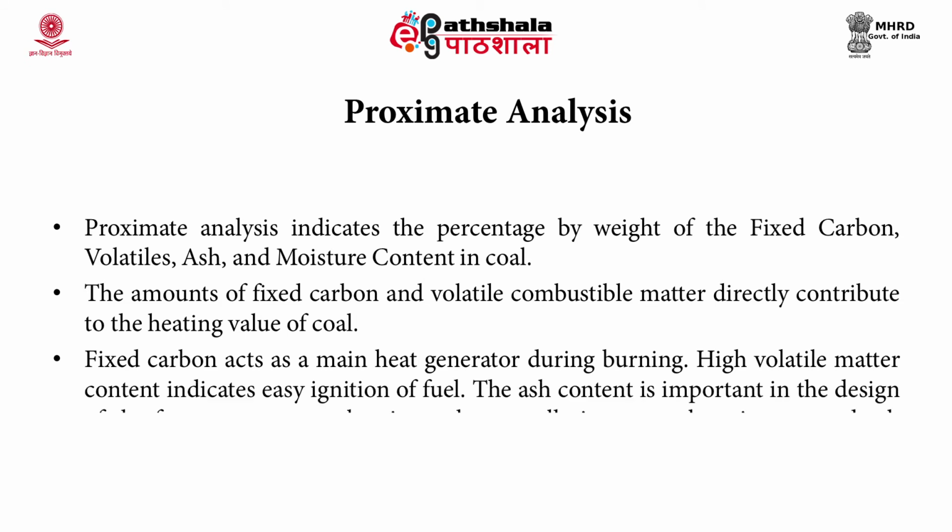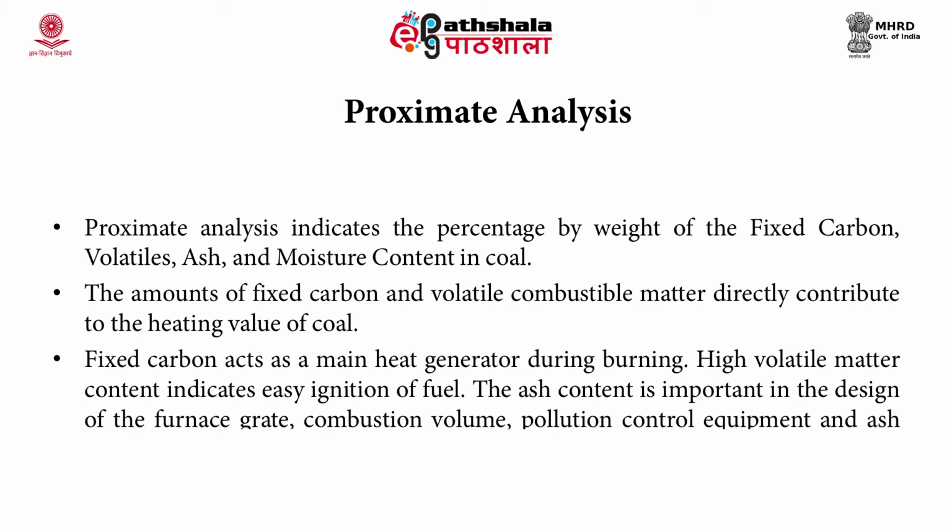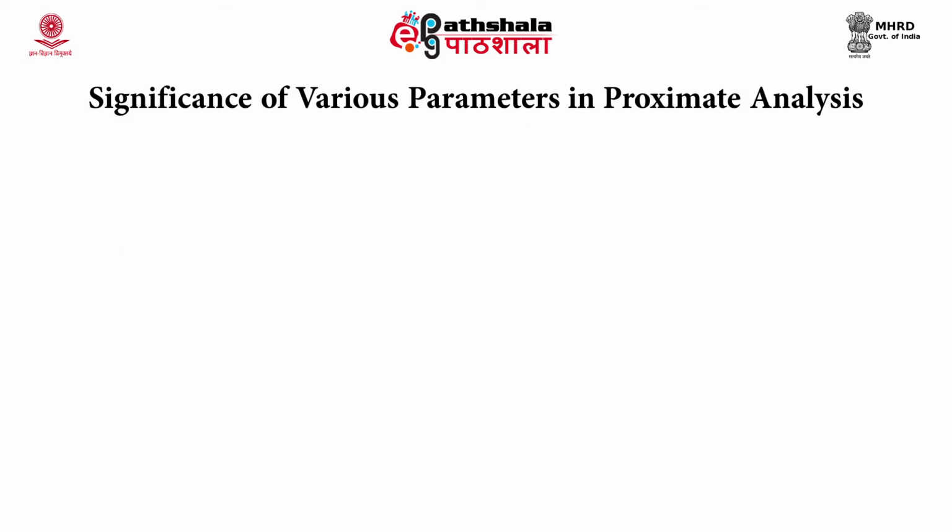The ash content is important in the design of furnace grade, combustion volume, pollution control equipment and ash handling systems of a furnace. So, once you know the components of the proximate analysis, you can improve the efficiency of the furnace or the engine. Now, what is the significance of these parameters in proximate analysis?